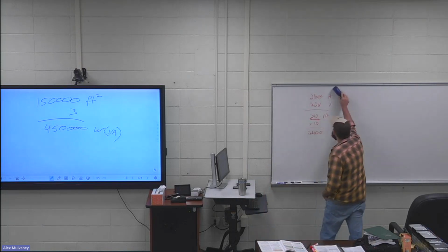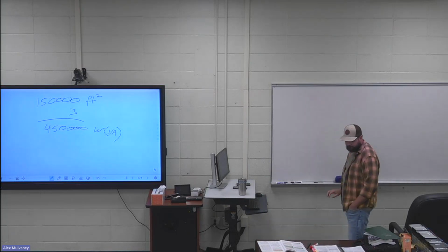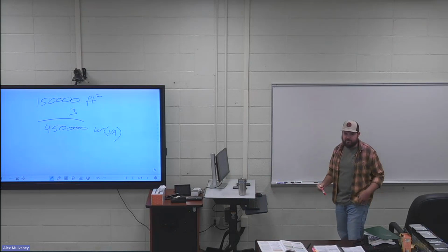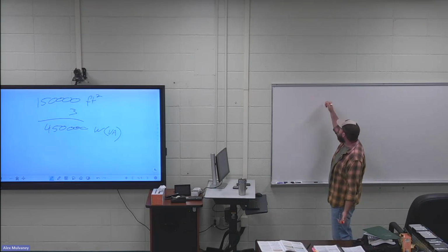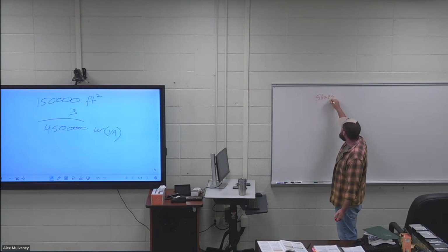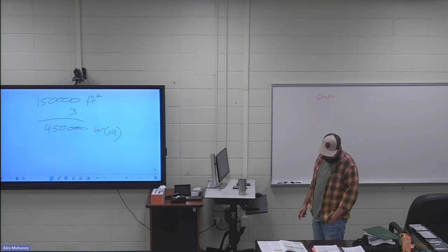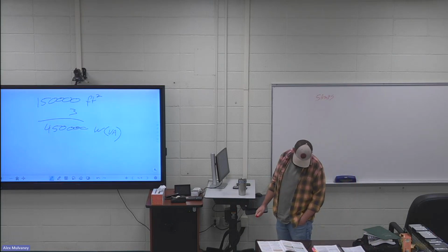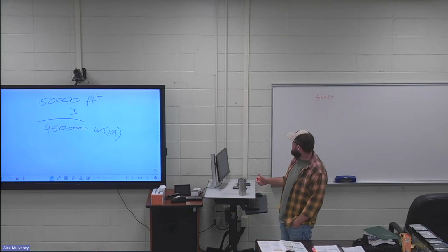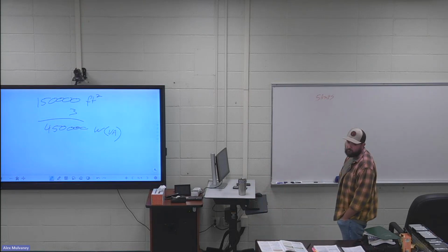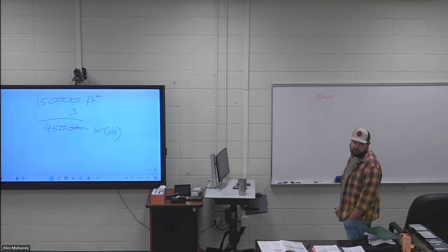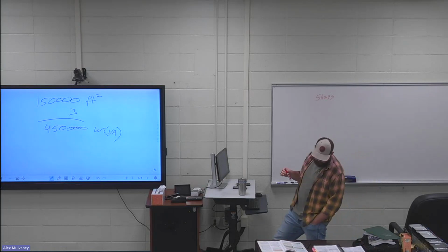So what this means is, if I have a continuous load, say I had lights outside of a business or something like that, and they run at 5 amps, and it's considered a continuous load, what do I have to multiply by? That last sentence before the note.